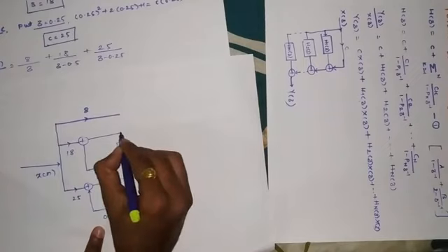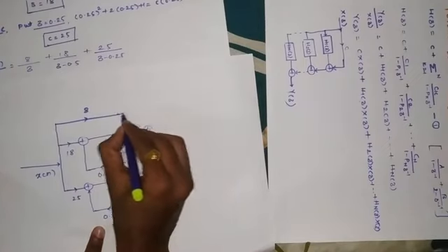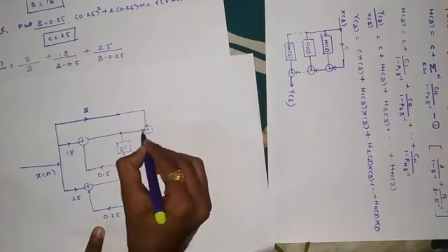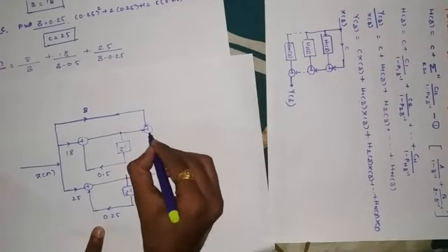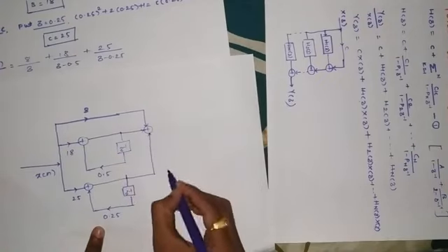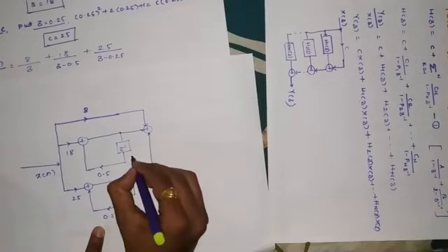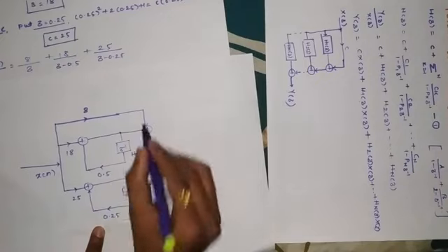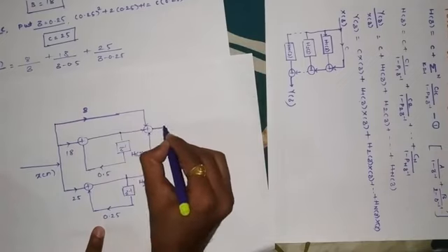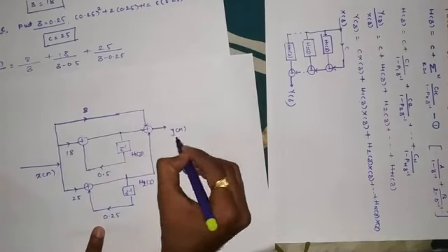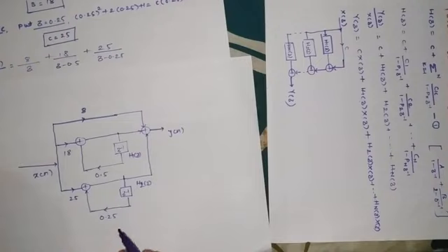So you can see this is an adder, and these three systems are added with each other. This is the output of the second system. This is H2 of z, this is H1 of z, and the first one is the constant, and finally you will get the output as y of n. So this is the parallel form realization of an IIR filter.